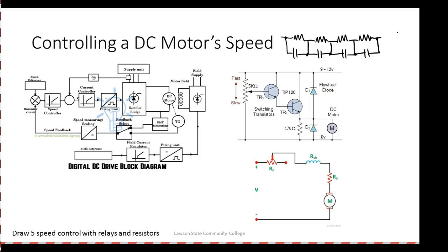And these were 5-speed cranes. That's what they were, and that's the only thing you did. If you were riding on the crane, you could hear the relays clicking while they were moving, and you had 5 speeds, and that was it, right? You understand? What we'd like to do, and here we're controlling it with a pot that's wired as a rheostat. So as I slow the motor down, the pot would get real hot, right? You understand? Because it's still going to produce that I²R, right?